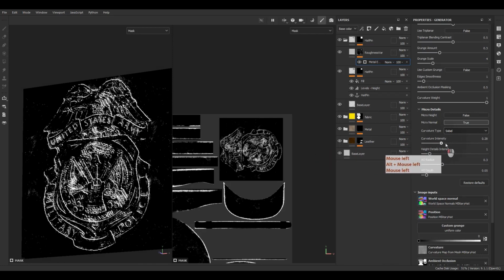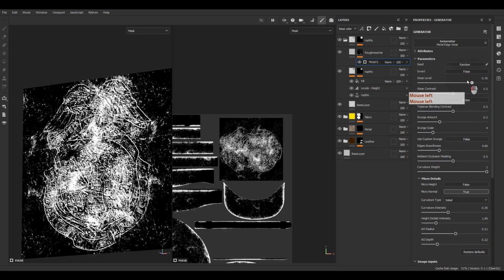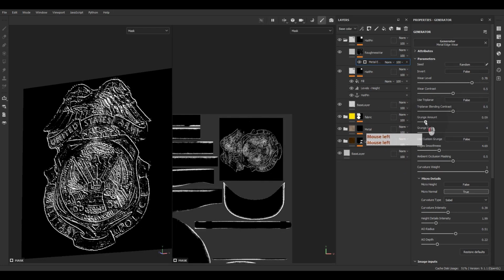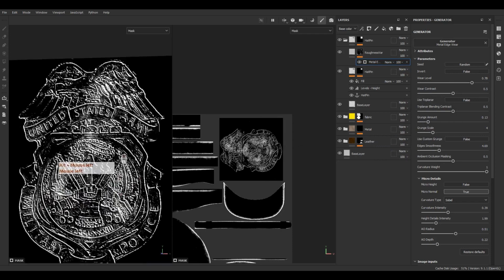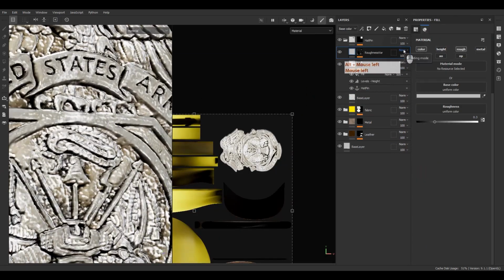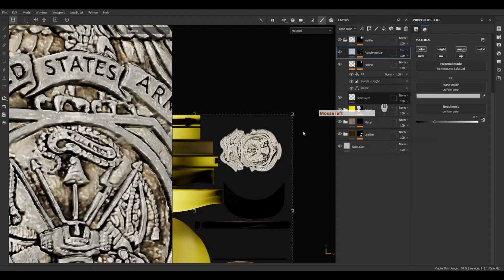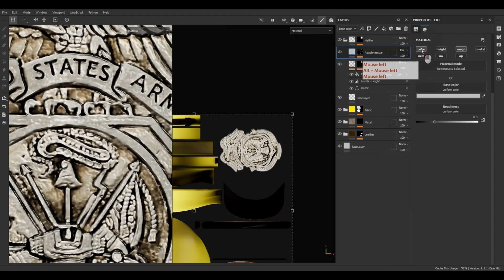Yeah, I can play with the curvature intensity, AO radius, and okay, maybe a variable grunge amount should be lower. Yeah, it's okay. It's okay. And I'm going to add the blending mode of the base color to multiply. As you can see, this is the effect.